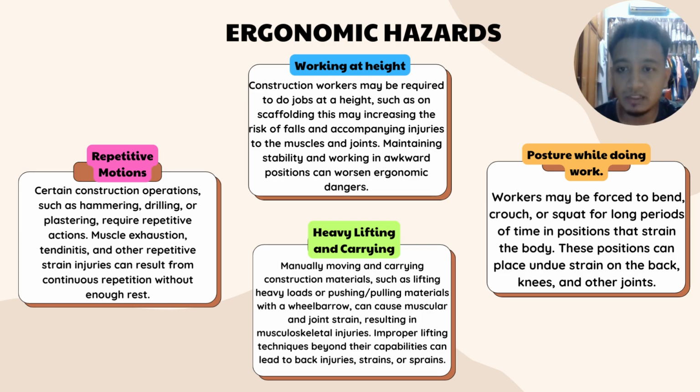So for the repetitive motion, certain construction operations such as hammering, drilling or plastering require repetitive action. Muscle exhaustion, tendinitis, and other repetitive strain injuries can result from continuous repetition without enough rest. So for heavy lifting and carrying, manually moving and carrying construction materials such as lifting heavy loads or pushing or pulling materials with a wheelbarrow can cause muscular and joint strain, resulting in musculoskeletal injuries. Improper lifting techniques beyond their capabilities can lead to back injuries, strain, or sprains.